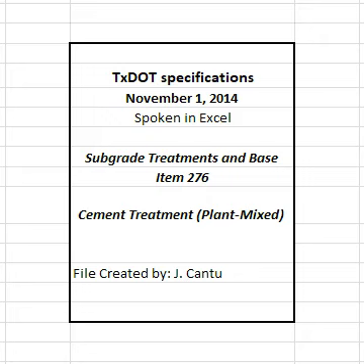4. Construction. Construct each layer uniformly, free of loose or segregated areas and with the required density and moisture content. Provide a smooth surface that conforms to the typical sections, lines, and grades shown on the plans or established by the engineer. Start placement operations only when the air temperature is at least 35 degrees Fahrenheit and rising or is at least 40 degrees Fahrenheit. The temperature will be taken in the shade and away from artificial heat. Suspend operations when the engineer determines that weather conditions are unsuitable.